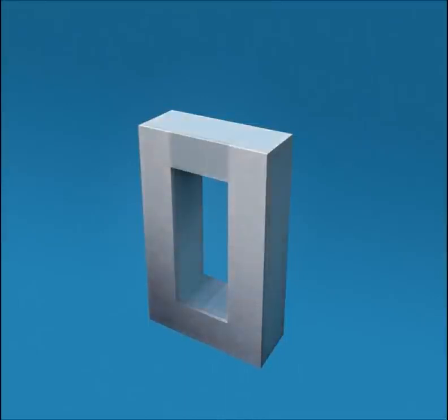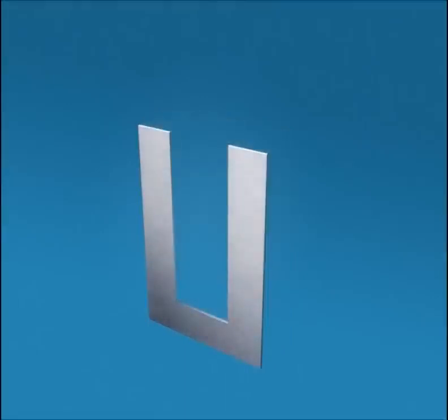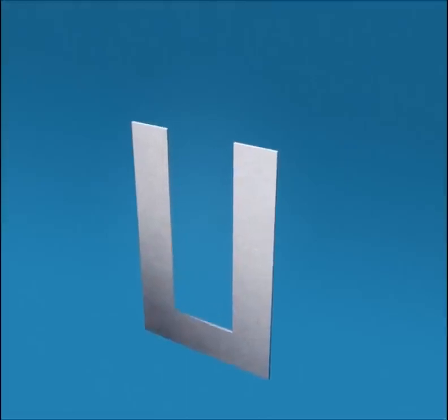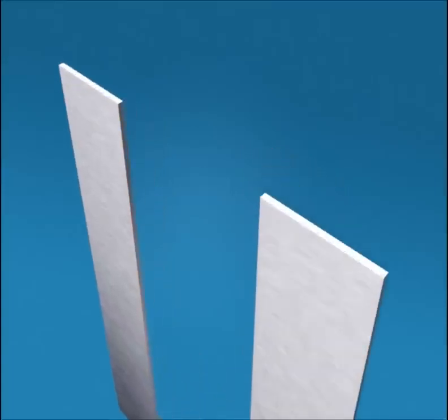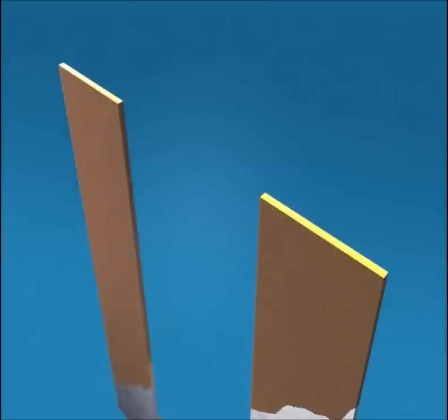The resistivity of the steel sheet itself is high, reducing the eddy current losses, while making the laminations very thin. The thickness of these laminations varies between 0.25 mm and 0.5 mm, and as steel is a conductor, the laminations are electrically insulated from each other via a very thin coating of insulating varnish or by the use of an oxide layer on the surface.